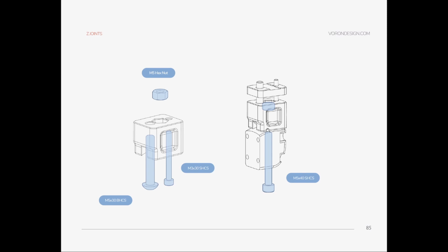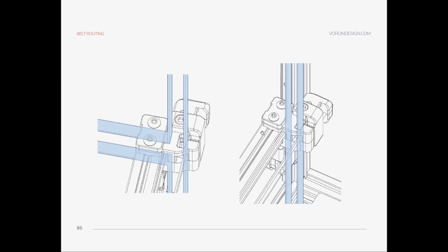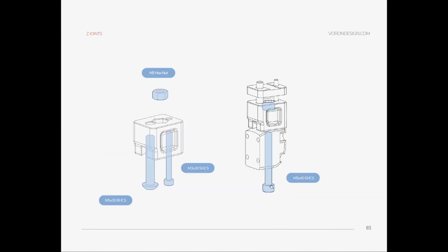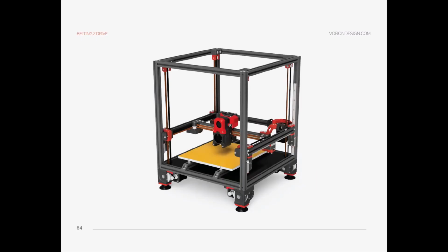It's helping this joint a little bit, not that much. And after that, put your gantry in place, and with this screw, put them together, but do not over tighten this one, because these parts have a little bit of room. Since it's a gantry, this corner, for example, can drop a bit, or for example, once your head is